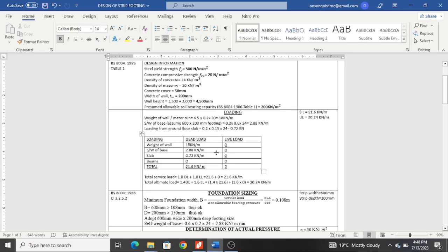From this type of construction, we did the substructure. We were proposing the substructure, and then you do the ground floor slab, which will cover that section up to where the walls are, and then you will do the superstructure walls on top of the ground floor slab.